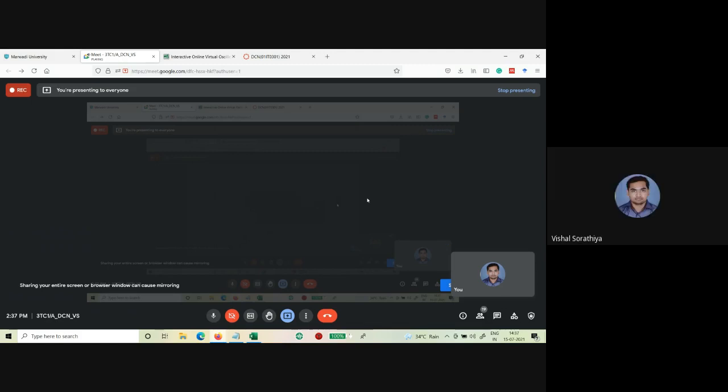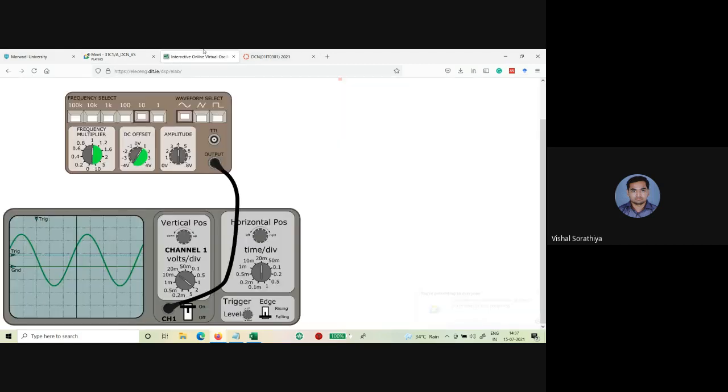Clamper. True, that requires a clamper circuit. If you attach a clamper circuit with a specific capacitor, the voltage is getting clamped. So overall your signal is getting shifted either to the positive side or the negative side. Truly, very good. So these are the functionality of the DC offset.